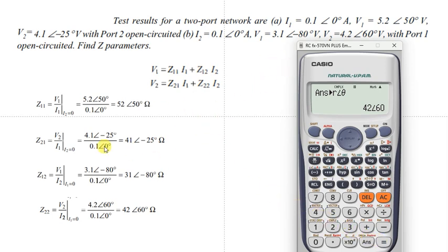So this is as good as 5 or 6 marks. All the readings will be there. Just if you remember all the two-port parameter network, these two equations, they will give one set with this port equal to 0, another set with this port equal to 0. For any equations, you are going to express two variables in terms of another two variables. In all the problems like this, they will give one set of readings with this port equal to 0, another reading with this port equal to 0, so that you can find the parameters, either this or this or this or this with the given readings.